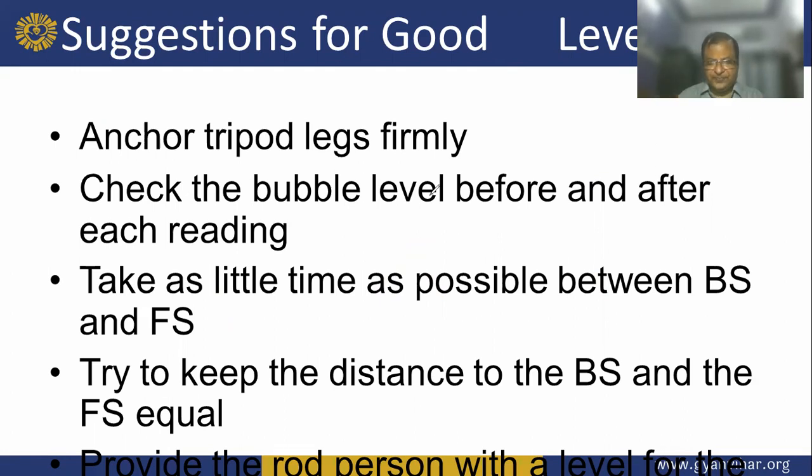Try to keep the distance BS and FS equal, and provide the rod person with a level to stand.